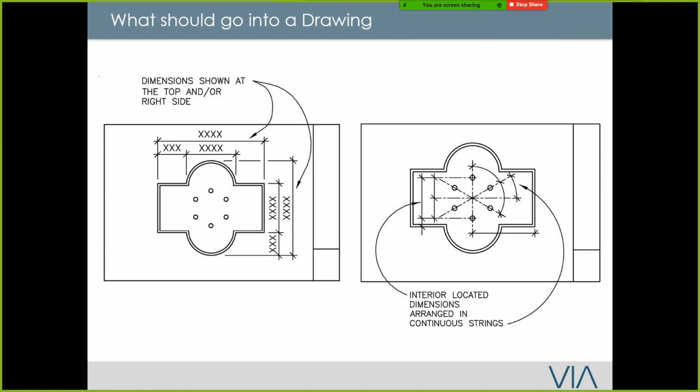All right. So when you're doing anything, let's say a building, you want to dimension the overall building. What we typically do is that when you dimension it, always put it on the outside. So what this shows us is that the overall dimension should always go on top, and whatever is intermediate should be below it. When you do the interior, it's the same way.